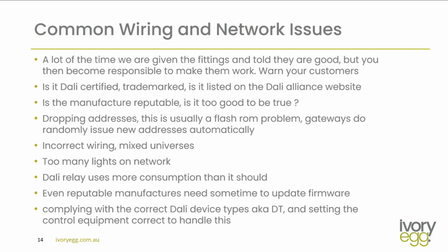Another really important one is: is there incorrect wiring? Are there loops? Have they put more cable than they're meant to use? Have they got enough power supply on the DALI network? Have they wired and mixed between universes? This is another common problem as well.